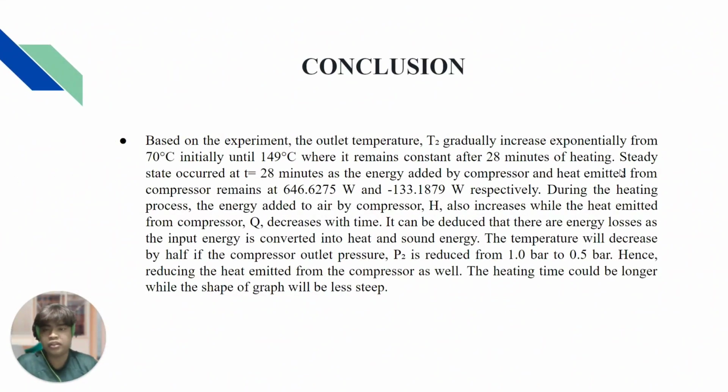So for conclusion, based on the experiment, the outlet temperature T2 gradually increased exponentially from 70 degrees Celsius initially until 149 degrees Celsius, but it remains constant after 28 minutes of heating.